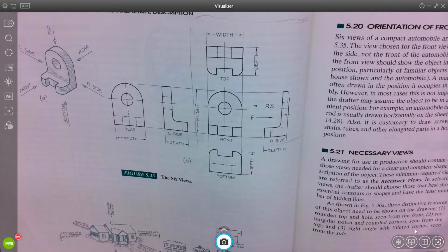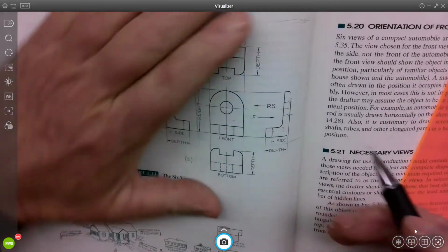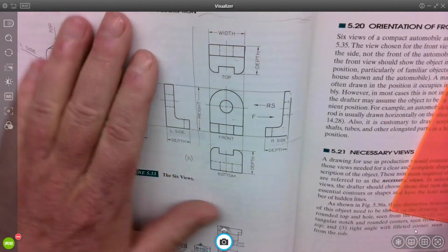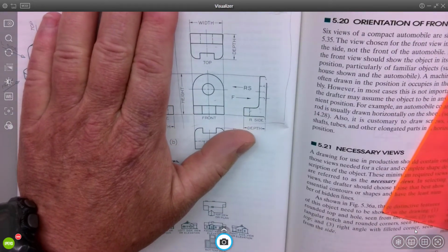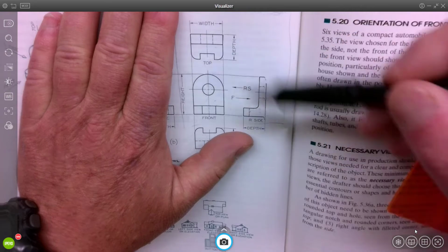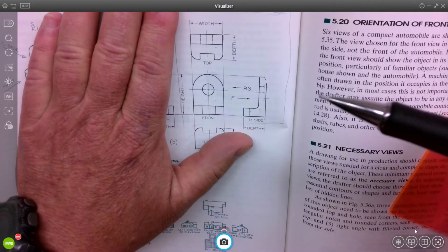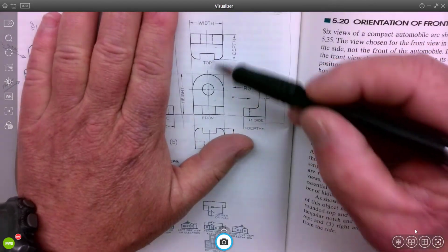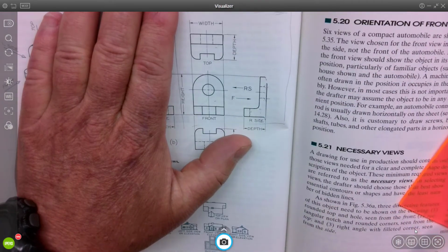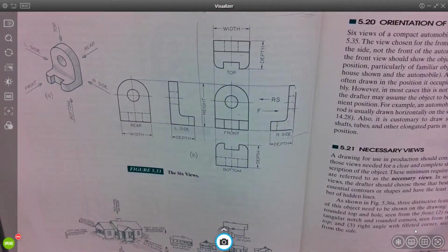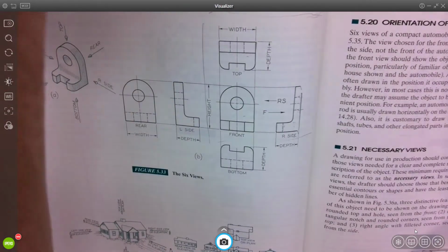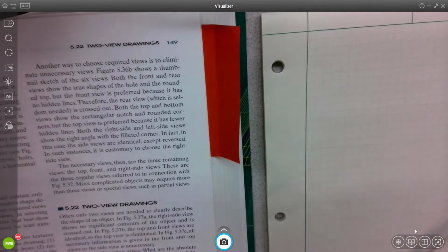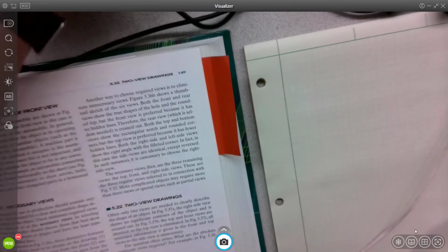And it takes practice, so we're going to practice a lot. All right. Notice also, just focusing on our views, which are front, top, and side, they actually have labeled their views. I need you to label your view too, okay? That's a requirement. We have to have our views labeled. So as you send me drawings, as I send you drawings, we understand that we're all looking at the same views.